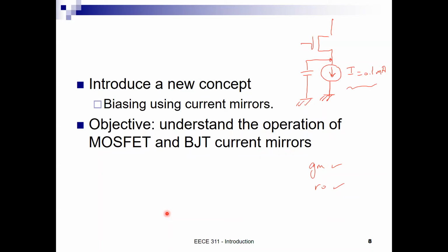In small signal analysis, what happens to this capacitor? It becomes shorted, right? It becomes shorted, and therefore I can study the gain of this circuit with these specific gm and ro that were derived from this current source. Great. Let me delete this.